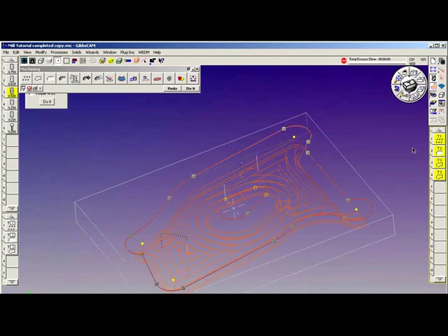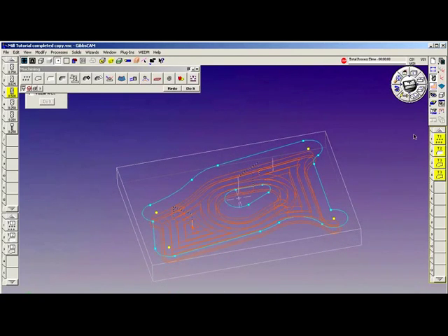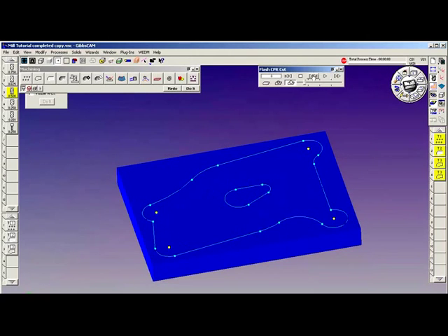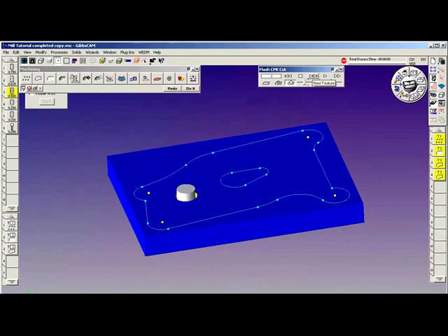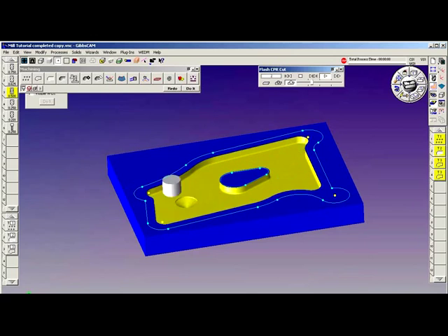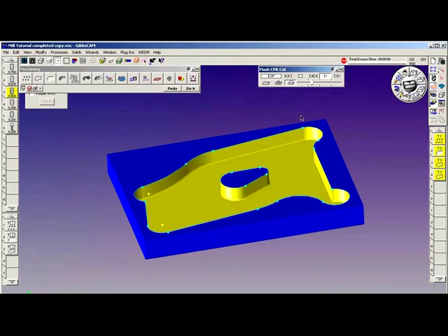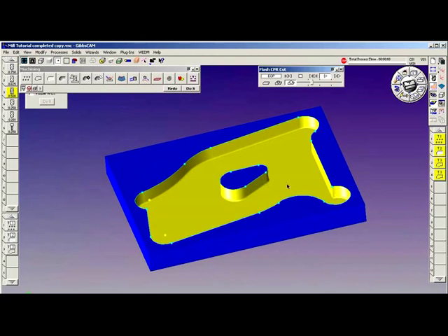Not too bad. As you can see, we took out all the material, and to illustrate a little bit slower, I'm going to slow it down. Here's operation number 1. It punches a hole in the part. Then the end mill comes in right at that same location and does the pocketing. You'll pick up, go back to the same location, and do it again. It goes around the island to finish it, and then we're good to go there.